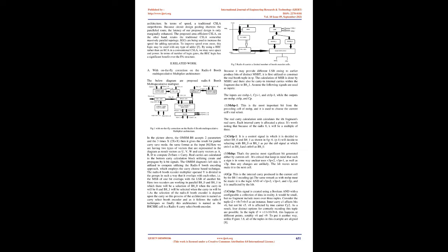In digital adders, the time it takes to transmit a carry via the adder limits the speed of addition. There are a few distinct adder processors and systems on the market. The time required for a carry to travel via a digital adder has had an effect on adding efficiency. Only when the previous bit position has been summed can another bit value be determined and a carry be transferred to the next place in a primitive adder. The total for every bit location is generated sequentially. Any adder's main speed constraint is the generation of carries. Now, utilizing the updated carry save adder, we can increase the performance of the architecture.